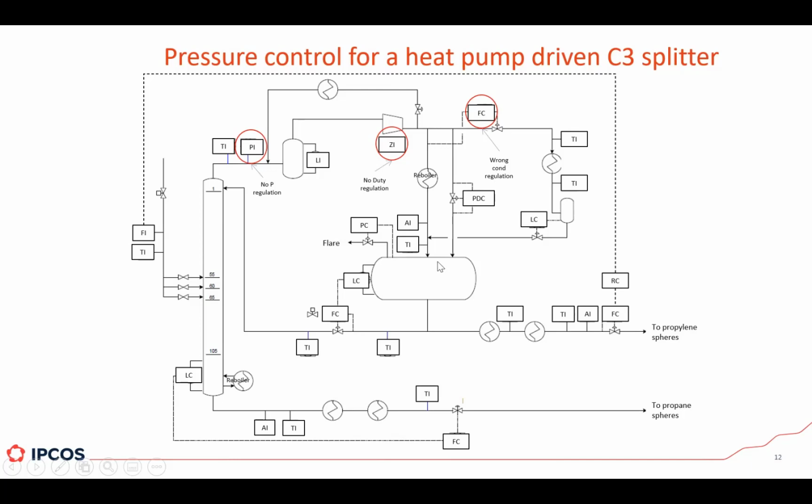This particular case is one in which the reflux ratio is close to 20. Why am I mentioning this? It means that the reflux flow is roughly 20 times as big as the top product flow rate.